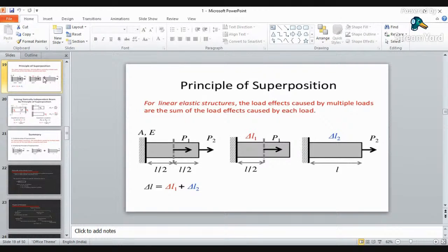Now, the simple principle of superposition is basically used to solve complex problems with multiple loads or reactions acting on the member. In that case, the superposition method helps us solve these problems by breaking the member down as necessary for each force acting on it. Once all our stresses or deflections for that point of interest are found, they can be added together to get the final answer.